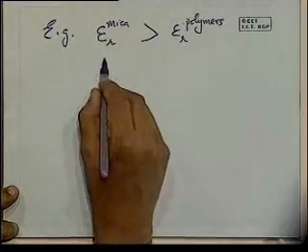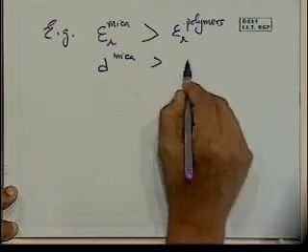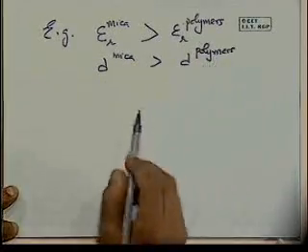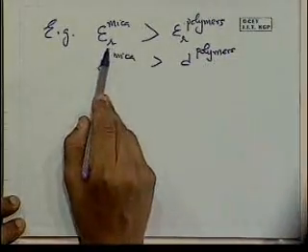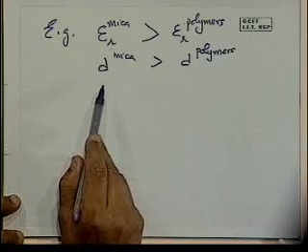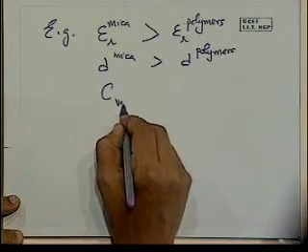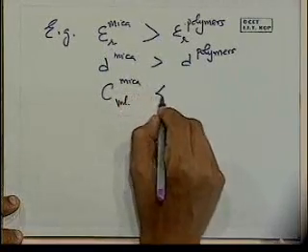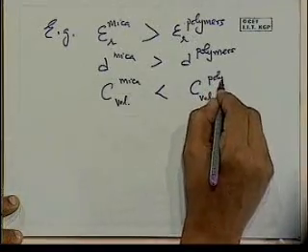Yet, because the thickness of mica is also greater than the thickness of polymers, polymers can be made as very thin films. The advantage that mica has in terms of dielectric constant is more than offset by the disadvantage it has in being thicker, and therefore the capacitance per unit volume of mica is less than that of polymers.